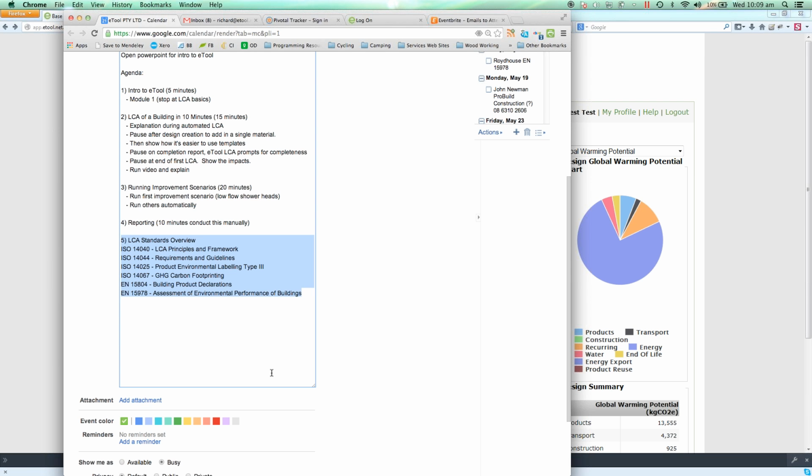I talked earlier about whether we should be claiming a credit for feeding electricity back into the grid. In order to meet all those standards in terms of carbon footprinting, PAS 2050, 14067, and also the Greenhouse Gas Protocol, providing you're not double counting, that is okay. What that means is that you have to ensure that you're not claiming a credit for energy that you're using in the building due to rooftop solar, but then also claiming a credit for feeding rooftop solar back into the grid. So if your grid mix accounts for rooftop solar, including your building, then you can't claim a credit for feeding that back out.